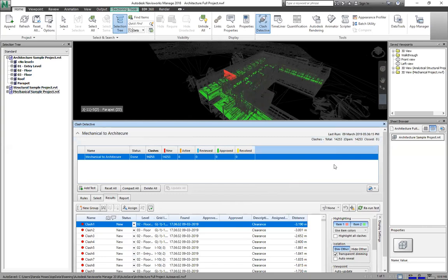The detection test noted that there are 14,253 clashes between these 2 elements. Now let us imagine that this is not done, and then on site we want to resolve 14,253 places where MEP is clashing with architecture. Of course, we can envisage an argument till eternity, but because we now begin to work across and manage the situation, we can shorten the periods. These issues can be determined even at the design stage.